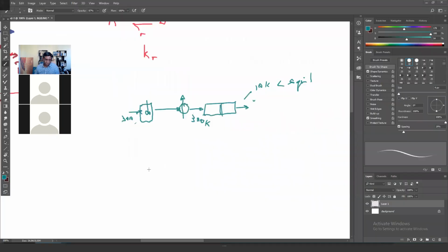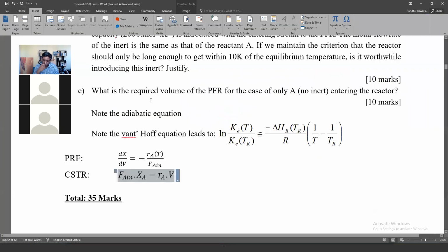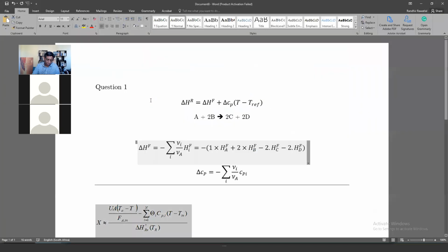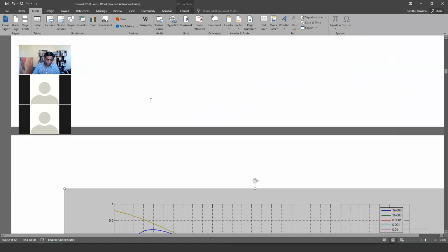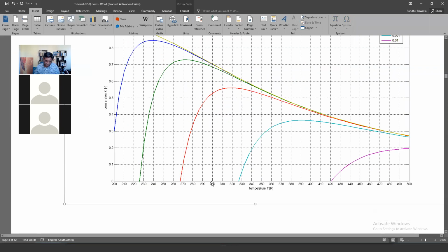And it makes sense because if you've got a fixed flow rate here, and then you start increasing the size of that space, then on average, you'll be spending more time in that reactor. So it's more time reacting. And so it makes sense that we should have a higher conversion. As we increase the volume, we'll get more conversion. So when we talk about moving around on this plane, and we say the conversion is rising, we are basically making that happen by considering larger and larger volumes.